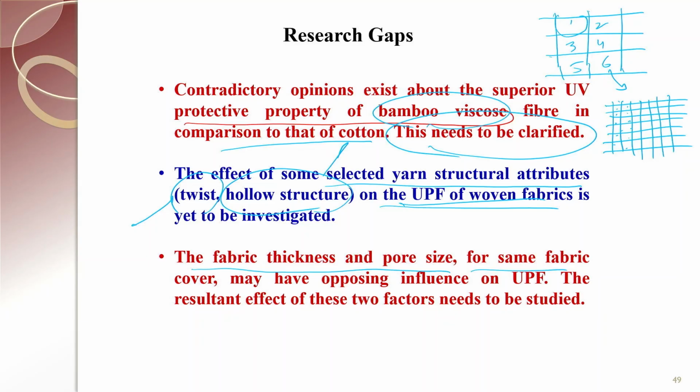So, that we have created, and we tried to understand the effect of the pore size, keeping the same fabric cover. How are these affecting? So, fabric thickness and pore size may have opposing influence on UPF. So, that we have tried to understand, and the resultant effect of these two factors need to be studied.